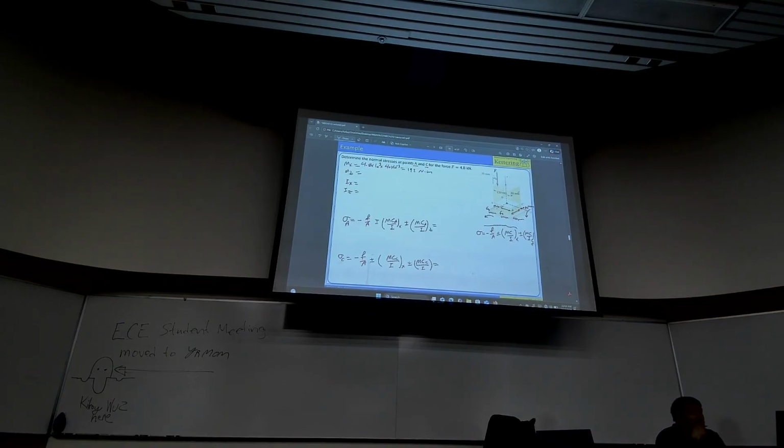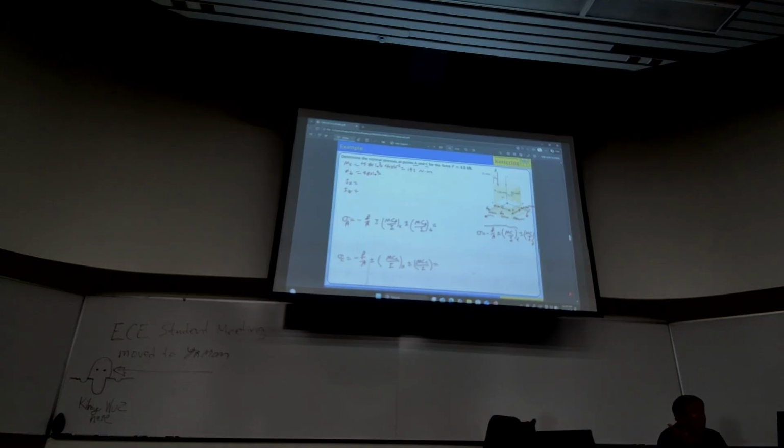All right, then Mz. If you just give me the distance, it would be 60 millimeters, or 60 times 10 to the negative. Again, the distance between force and z-axis. 35 millimeters. Again, force and z, not a number that you see there. Between force and z, z is in the middle. Force is 35 away from the left side. Go for it, he knows it. Think further.